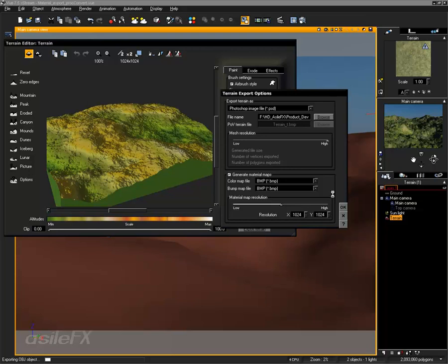And I also want to note that whenever you save in the image format, or at least Photoshop format, if you look in the lower part of the screen, the lower left, where it's showing the progress, normally it'll say the format it is saving in, which would be, if it was a 3ds file, it would say exporting 3ds object. Well, in this case, even though we're exporting a Photoshop file, it will say exporting an OBJ file, so OBJ object.